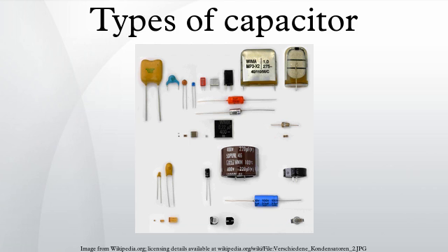These are 100 kHz, 1 MHz or 10 MHz for non-electrolytic capacitors with C_R ≤ 1 nF, 1 kHz or 10 kHz for non-electrolytic capacitors with 1 nF < C_R ≤ 10 µF, 100 to 120 Hz for electrolytic capacitors, and 50 to 60 Hz or 100 to 120 Hz for non-electrolytic capacitors with C_R greater than 10 µF.